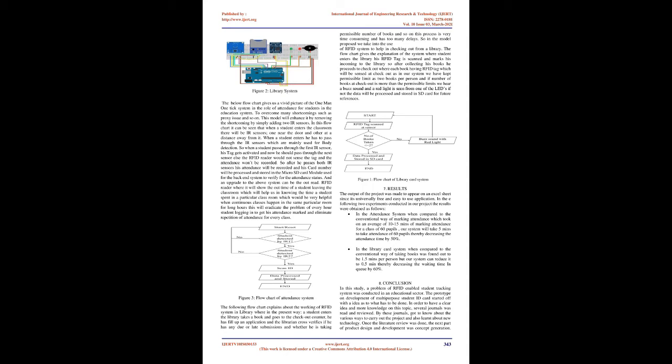Lastly, coming to the output voltage of the Arduino, it has two output voltages. One is the 3.3V output connected to the micro SD card module and the RTC, and the other one is the 5V output connected to the buzzer. Also, two resistors of 220 and 330 ohm value are added to the circuit, which will help in stabilizing the current during any fluctuation. The power source for the Arduino can be of two ways, one being from the USB cable using an electronic device, or the other being a 5V adapter capable of producing 500 mA, used to run the microcontroller and the electronic equipment connected.